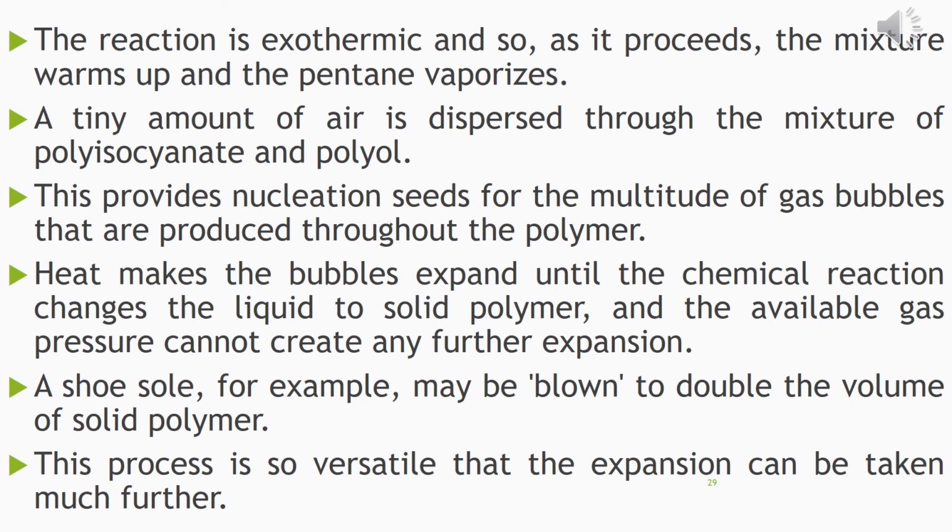The vaporization of the pentane due to the exothermic reaction provides nucleation seeds for the multitude of gas bubbles that are produced throughout the polymer. So this will initiate the bubbling. Heat makes the bubbles expand; they become bigger and bigger.